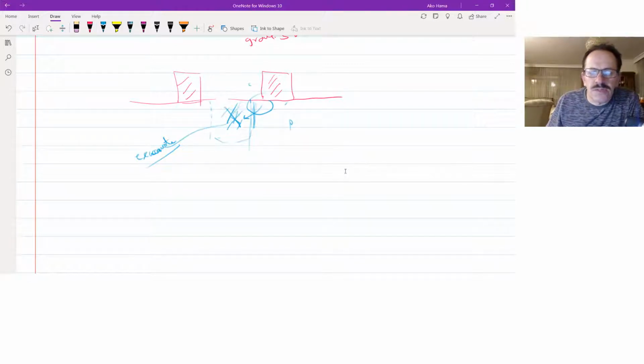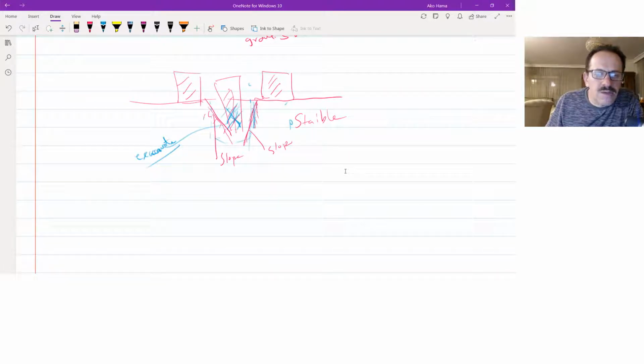Usually we have two options. First of all, this wedge: when we have an excavation like this, maybe you just excavate like this, and you see that this excavation or this slope of the soil will be stable enough to build your building here. So you may excavate and make a slope for this lateral pressure, and make this soil stable so that it does not drop down or fall in this way.